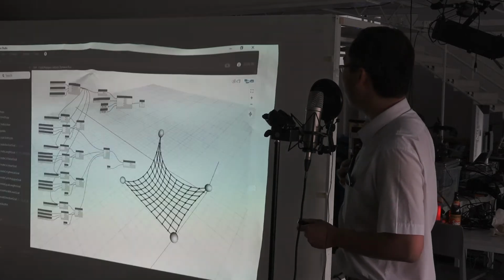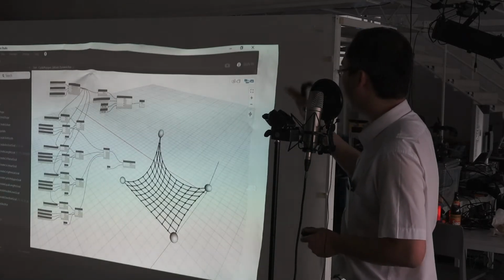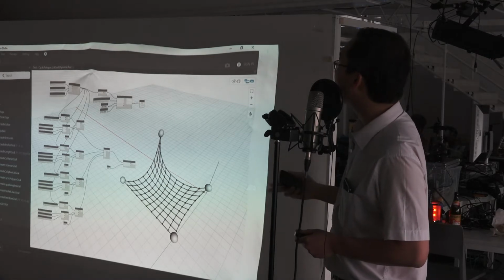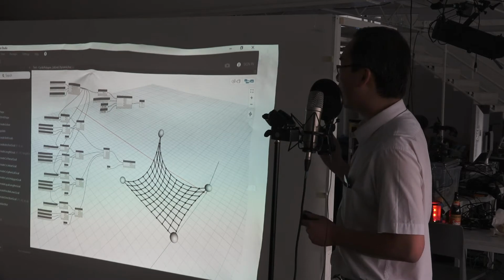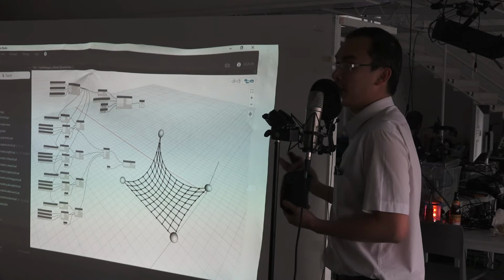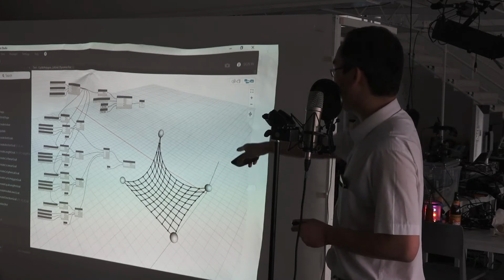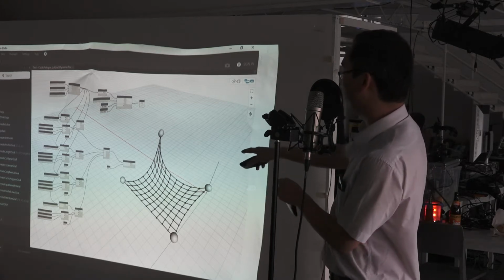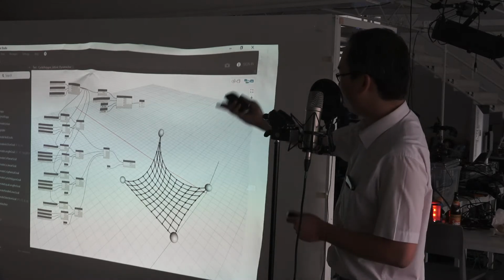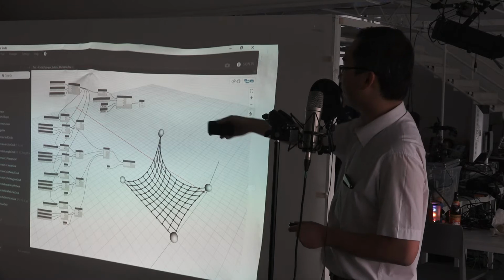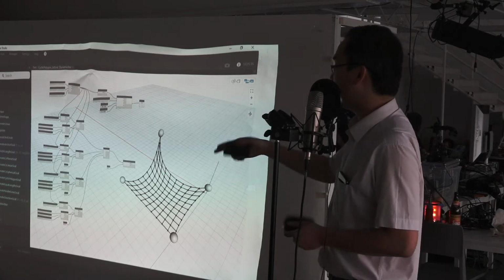So over the past 2 days, I developed this custom plugin for Dynamo called Dynashape. Basically, it consists of a geometric solver that takes in a set of constraints, and these constraints act on the particles or the nodes. At the moment I have already implemented some of the basic constraints, which I call goals.